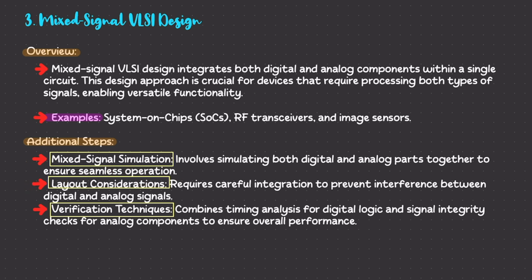Second would be your layout consideration. See, we are carefully integrating the digital and analog components. Why are we doing it? To prevent interference. Third one would be verification techniques. We are combining timing analysis for digital logic and signal integrity checks for the analog components to make sure that the overall performance is good and it is working as intended.